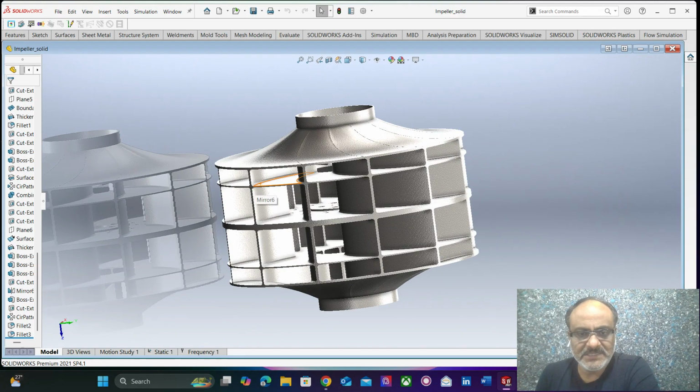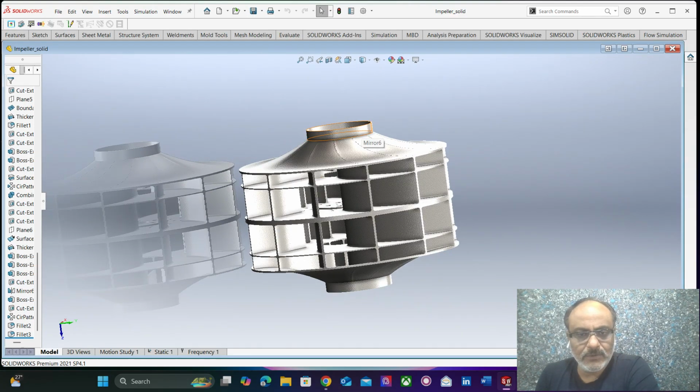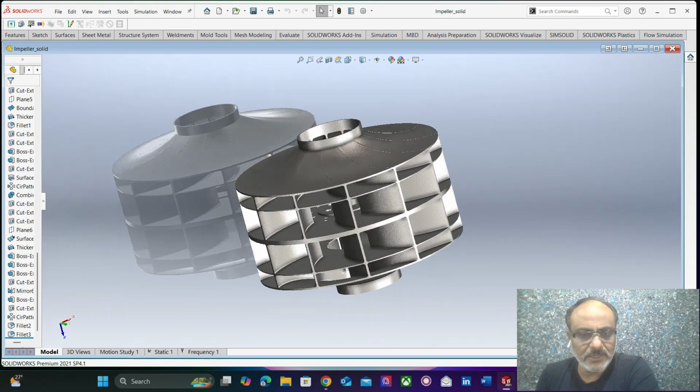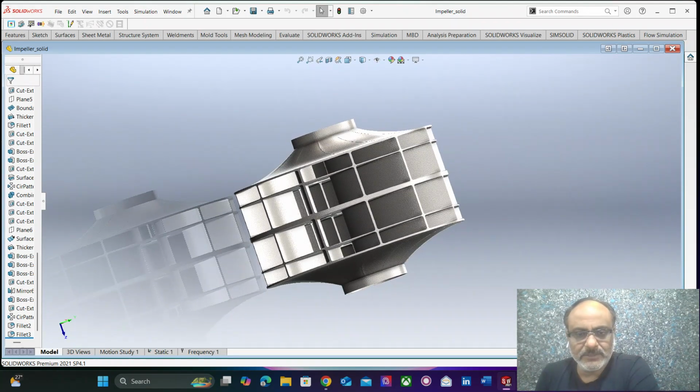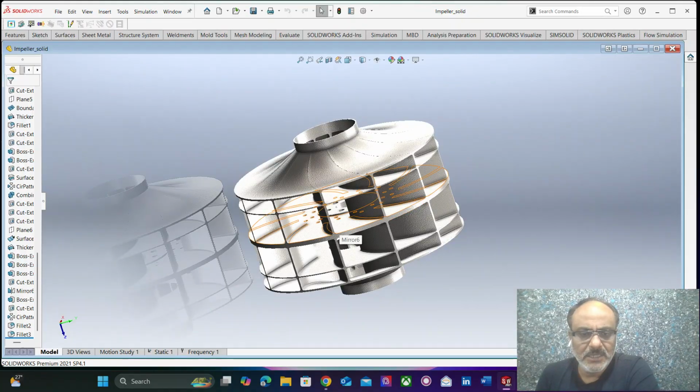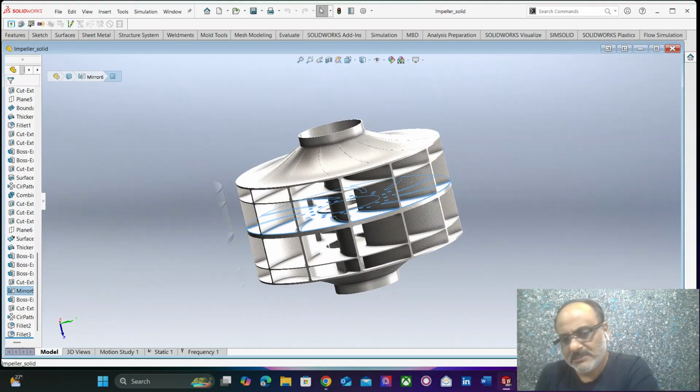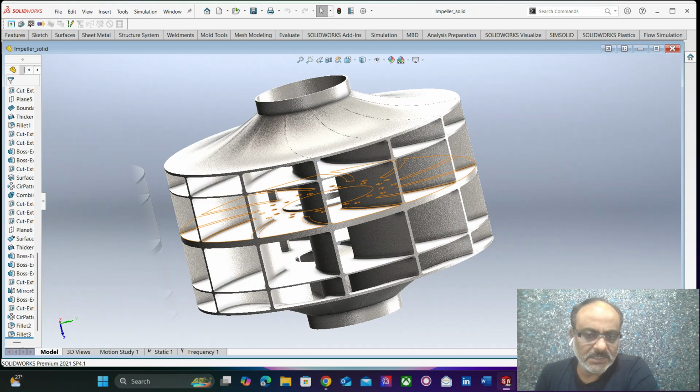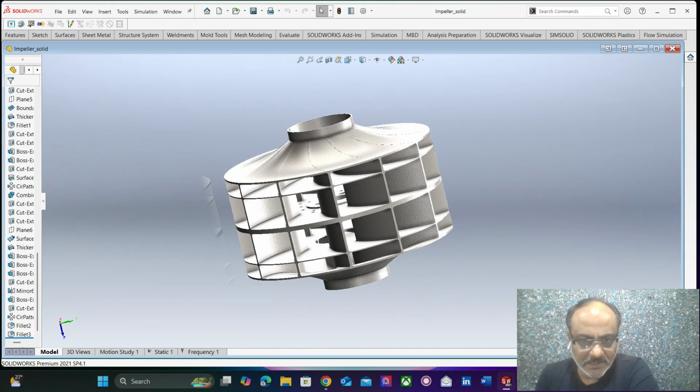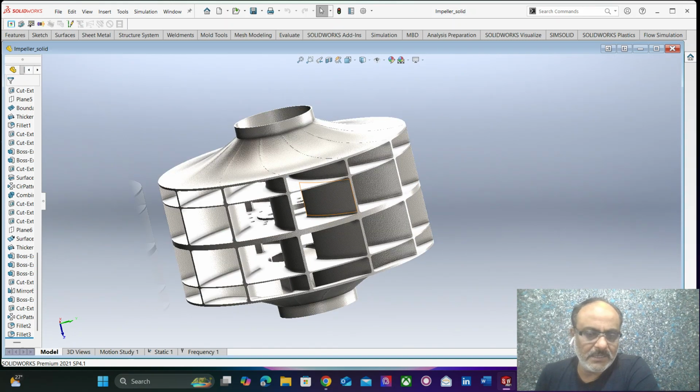Now there is a specific reason for the crown on this structure. The initial thickness of the disc was more than 30 mm. For this design, the thickness was considered to be about 22 mm, and the remaining 8 mm was split and equally distributed onto the top and bottom stiffeners.